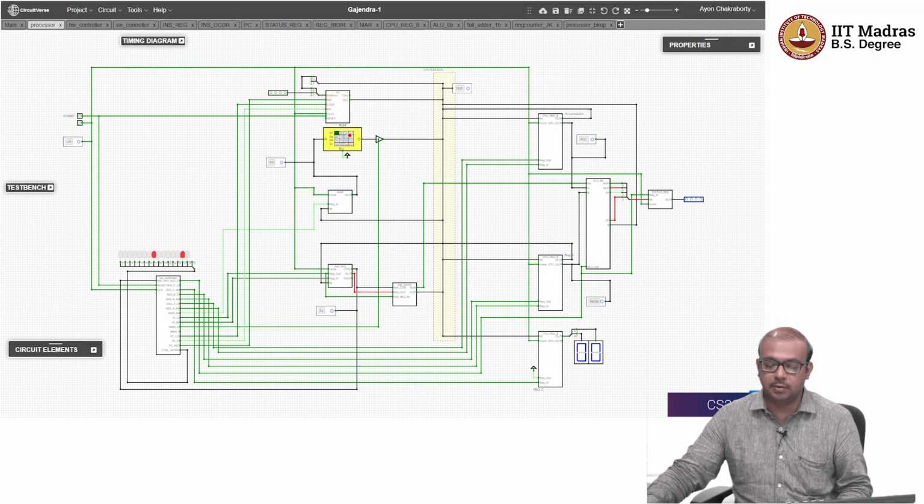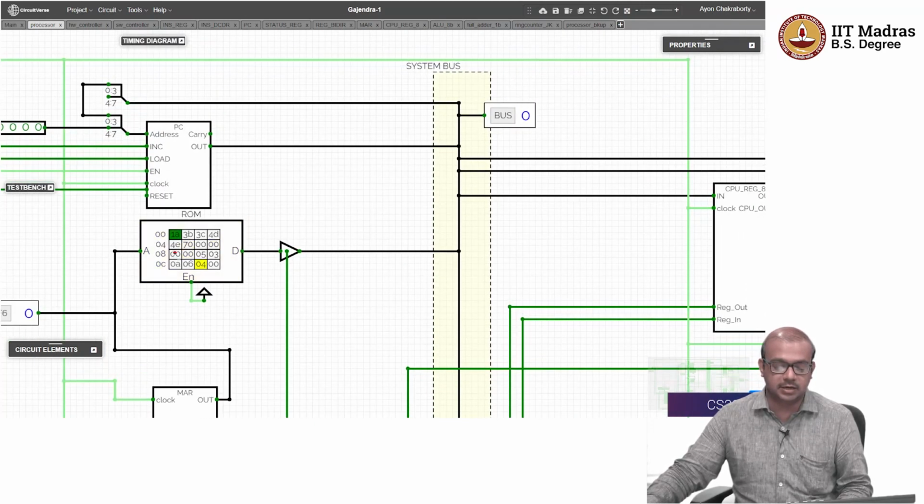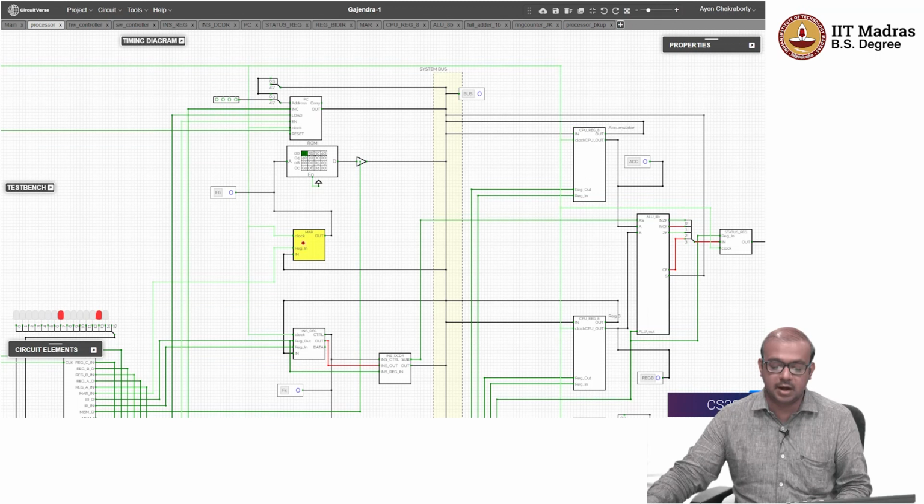This is the memory where we are storing both the data as well as the program. It has stored some program. As you can see, there is some machine code written, 1A, 3B, 3C, 4D, whatever it means, we'll come to that later. The top part is the program, and the bottom part, this 5, 3A, is the data. Maybe we are doing some calculation with the data. Then you have this MAR, which is your memory address register. Its output is directly input to the address of the memory, and it will read from the common bus.